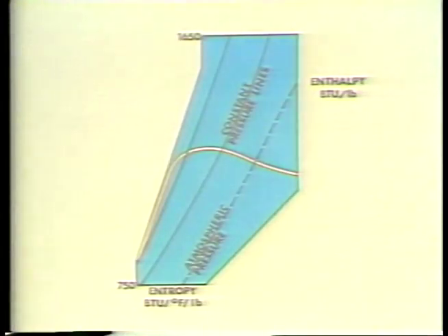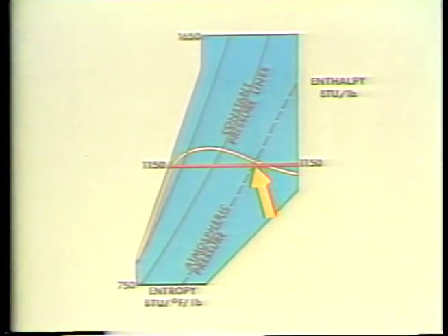and trace it out to the edge of the graph where enthalpy is indicated. For example, if you need to know the enthalpy of steam at saturation temperature and atmospheric pressure, you follow the saturation line until it intersects with the pressure line at 14.696 psia. Then you follow the enthalpy line out to the edge of the graph. Using this method, you find that the value for enthalpy is a bit more than 1,150 BTUs per pound. In actuality, the enthalpy value given in the steam tables is 1,150.5 BTUs per pound. For most purposes, the approximate value from the Mollier diagram will be close enough.